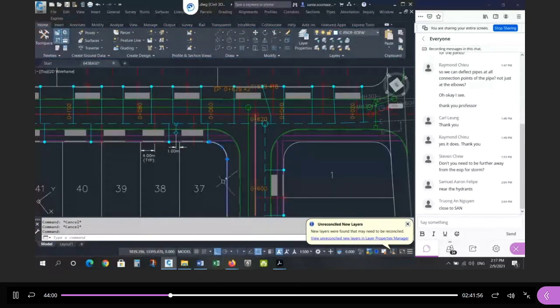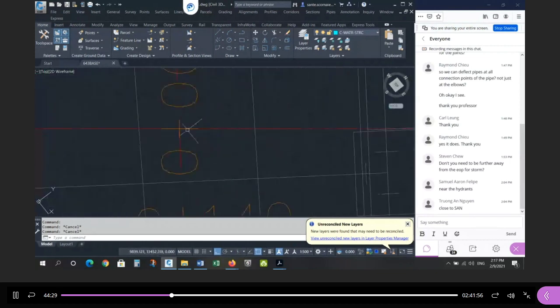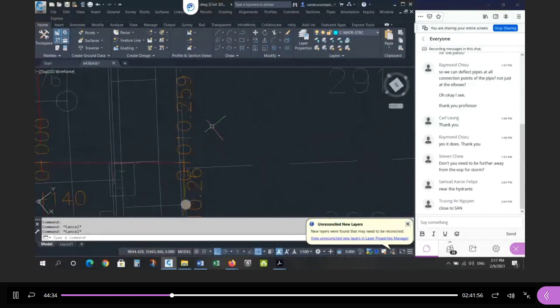Maybe your offset wasn't exactly 8 meters to center. Maybe your radius in the corners was wrong, right? If the geometry length is wrong, if the total distance to the end is wrong, then the geometry along the way has a problem. Okay, so you'll see I gave 2 marks, and if you didn't get 2 out of 2 for the alignment, then you have to fix it. Okay, and I gave 2 marks for the alignment of Street A and 2 marks for the alignment of Street B. If you did Street A correctly, 0 should be at the intersection of the 2 center lines, Ledger Way and Street A. It starts, because it's not exactly 90 degrees, at negative 10.259.